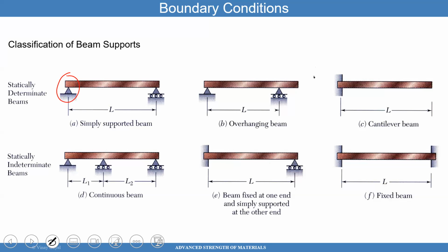The same thing here. And in here, the deflection is known to be 0, and the slope is also known to be 0. So both deflection and slope are 0 in this case. But at this boundary, I don't know the deflection and I don't know the slope. So those are things that you could find in this problem.